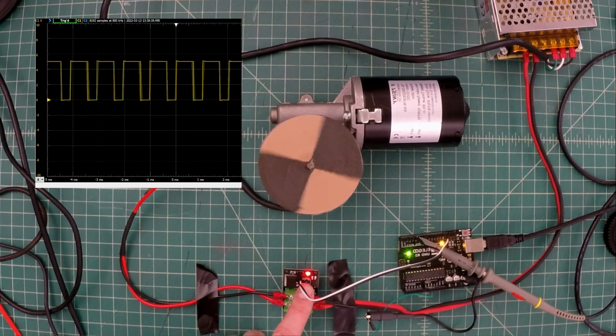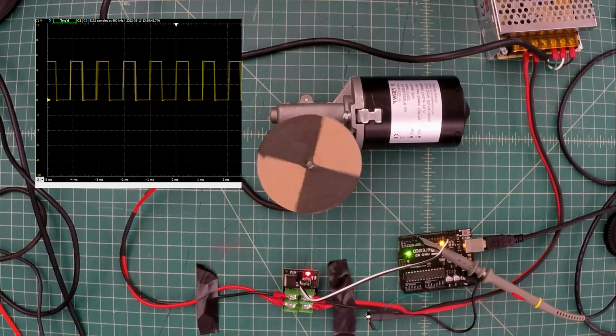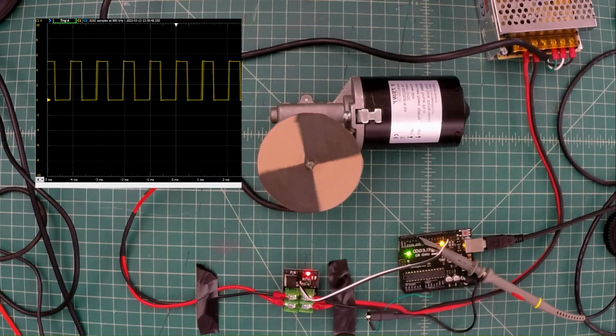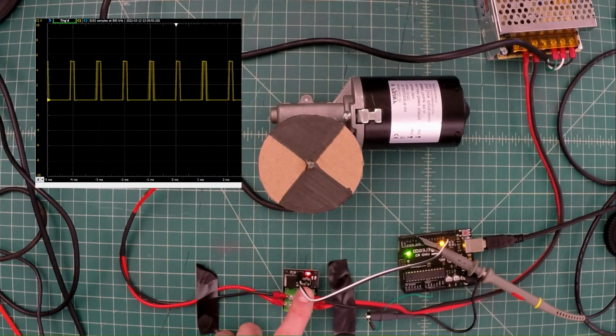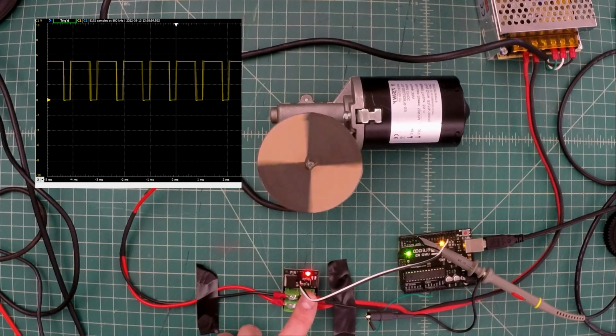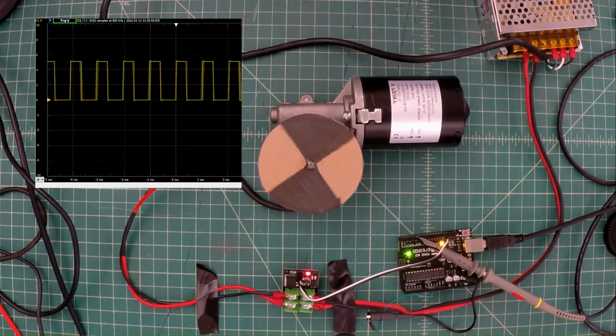Now you'll also notice on our transistor module, there's a little LED that lights up with the pulse width modulation signal. So this is exactly the same as what we did in class when we were fading an LED with pulse width modulation. We're doing the same thing on that board. So you can see the LED gets brighter when the PWM duty cycle increases, and then it fades back down as the duty cycle decreases.